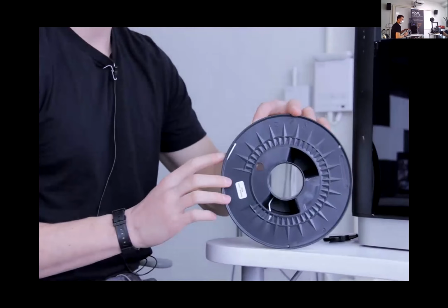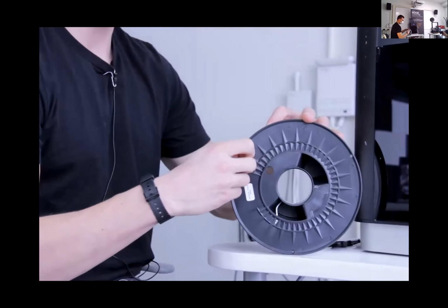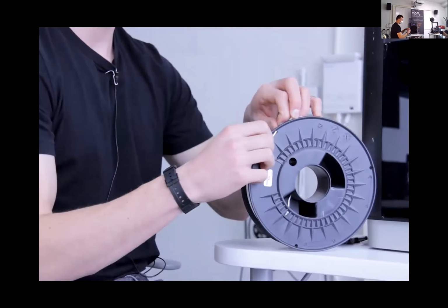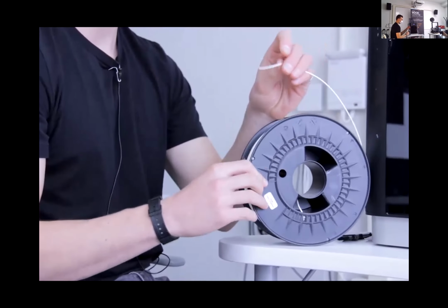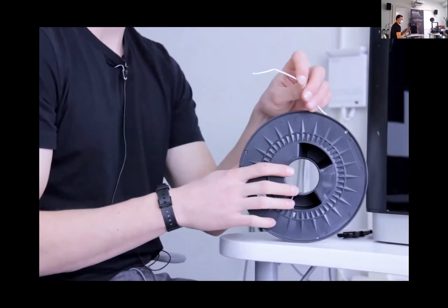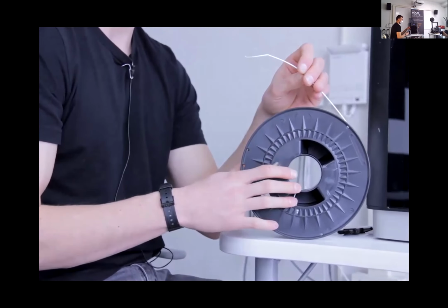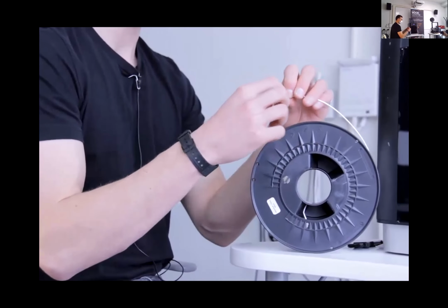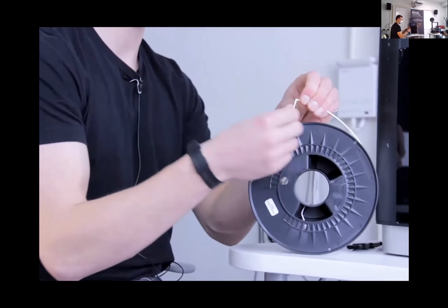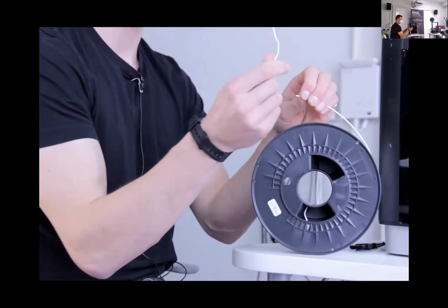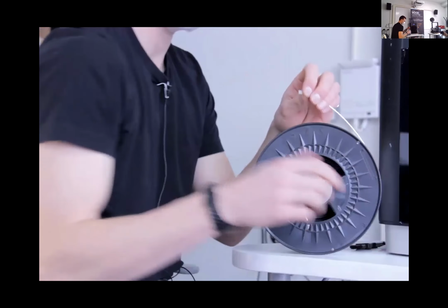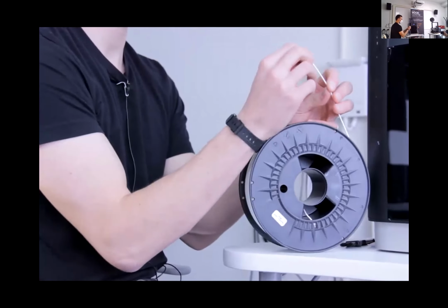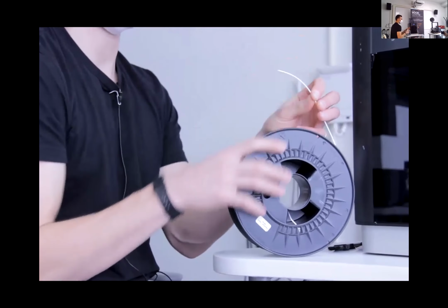Here's the end of the roll. I guess the start of the roll, they always thread it through the roll itself so we can keep track of it. You can see here that this is very bent and this isn't going to go through our printer nicely. We need a nice smooth filament. So I like to just break off that bent piece and we can discard that. We don't need that anymore. And we have our new roll of filament with a nice clean end ready to go into our printer.